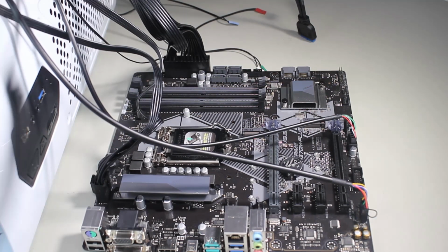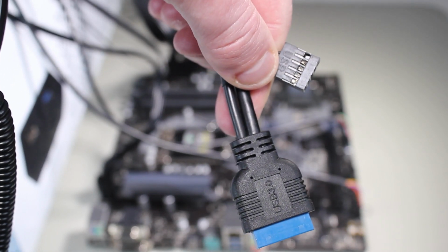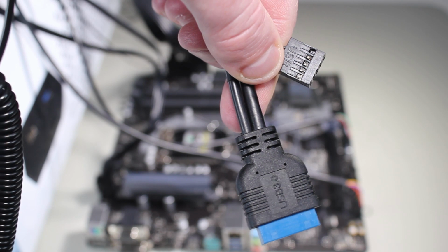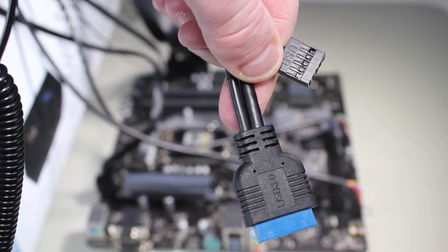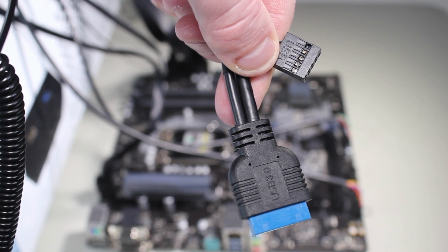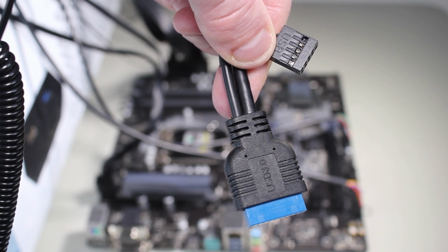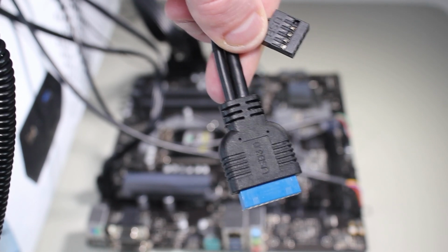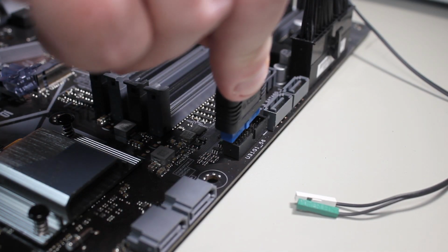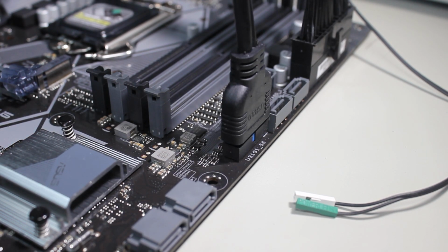The next connector I will connect is the USB 3 connector. You will notice that it is a larger connector and is generally blue in color. There is a second connector attached to the same connector. This is a USB 2 connector. Only use one. If the motherboard supports USB 3, use the USB 3 connector. If the motherboard does not support USB 3, use the USB 2 connector. The USB 3 connector, like the other one, just clicks into place. You will notice that it has a blue notch that can be seen in the middle of the black plug. This notch prevents the USB 3 cable from being plugged in the wrong way.